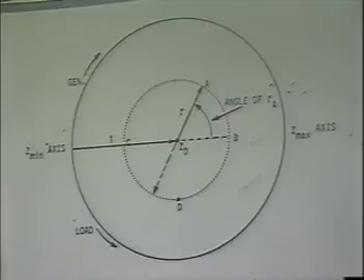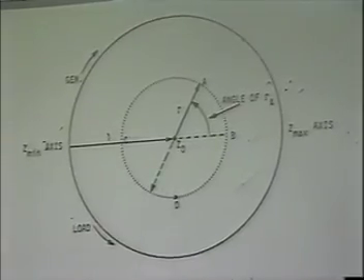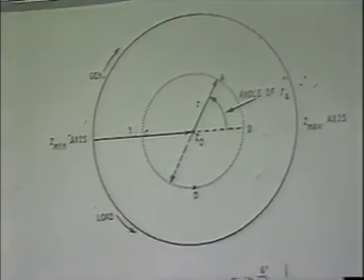Could I call it the return loss circle? Yes, because every point on there is uniquely related to the VSWR, isn't it? So really, this circle represents any propagation characteristic: return loss, mismatch loss, reflected power in percent, gamma, and the voltage standing wave ratio. All of those parameters can be looked upon as the circle because it's the same magnitude.